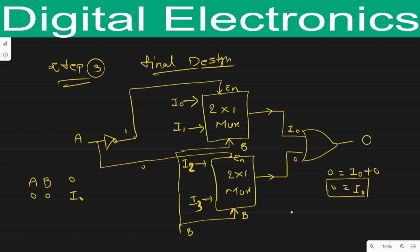Okay, now consider our second case, when A equals 0 and B equals 1. According to the truth table, we will find output as I1. So let's see what happened when we take A equals 0. Similarly, the output of the NOT gate will be 1. It activates the upper multiplexer, but because of this 0, the lower multiplexer will be deactivated again.